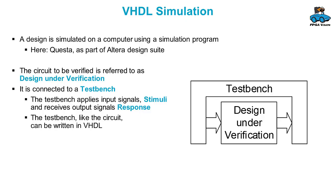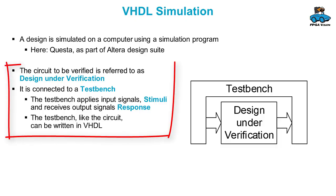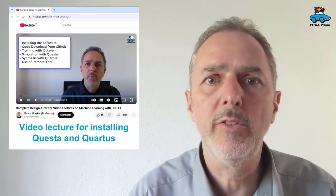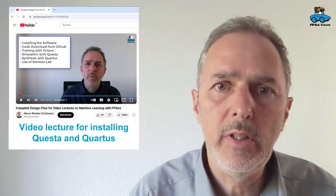The circuit that we want to verify is referred to as the design under verification. And what we also need is a test bench. The test bench connects to the design under verification and it provides the input signal to the design, the stimuli, and it receives the output signal, the response. The test bench, like the circuit, can be written in VHDL. The installation of the Questa simulator and the Quartus design suite is described in a separate video that you can find on the channel.